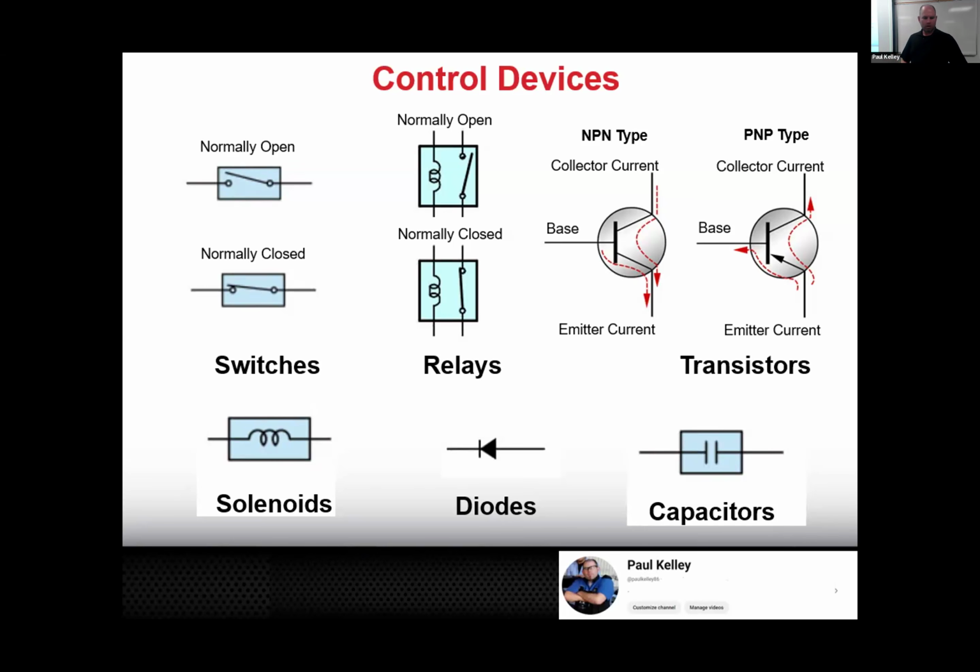So in your story, you'd be specifically saying, they may not always call it a transistor. Sometimes they'll call it a driver. Be like, oh, it's got an open driver in the ECU for the fuel pump. And if I read that on a write-up, I'd be like, okay, this person tested some stuff. And in your story, you might even say, I tested for voltage right here, and that may be at terminal 72 of the ECM, and it had 0 volts, right?